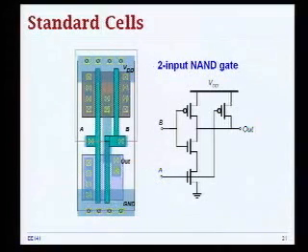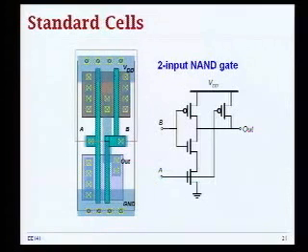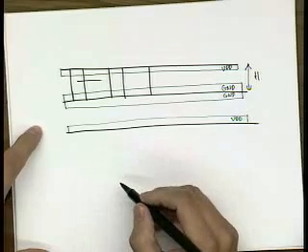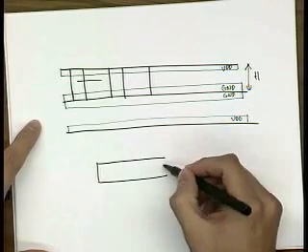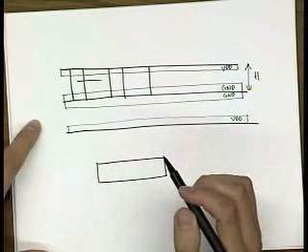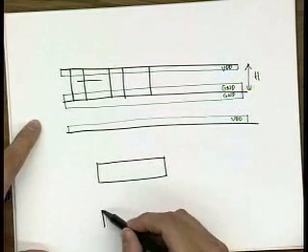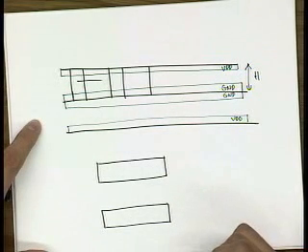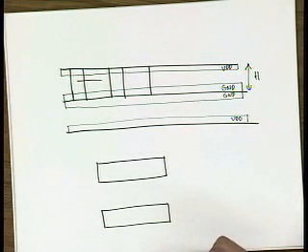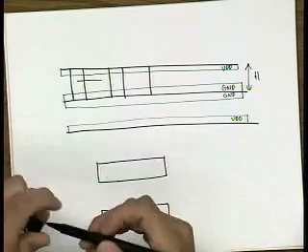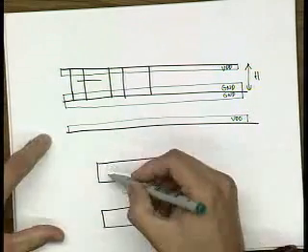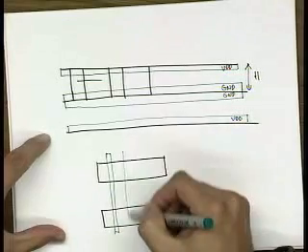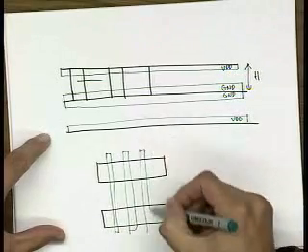So now, what you really need to learn here is what to do if you have really complex cells. Now the question is, in order to achieve the highest integration possible, what would you like to have is basically this following strategy. What you would like to have is a continuous strip of diffusion for the PMOS, and then a continuous strip of diffusion for the NMOS, such that when you connect the transistors in the pull-up and pull-down network with the gate signals, all you need to do is just put vertical polylines that correspond to your gate signals.